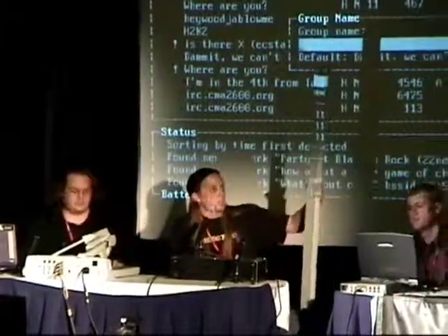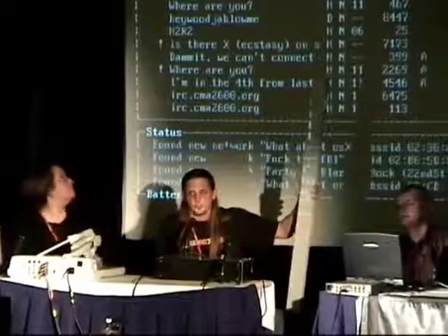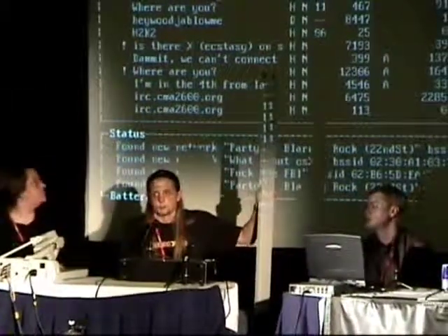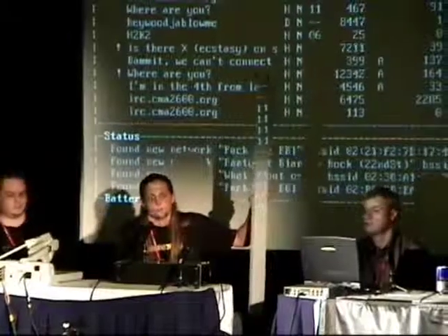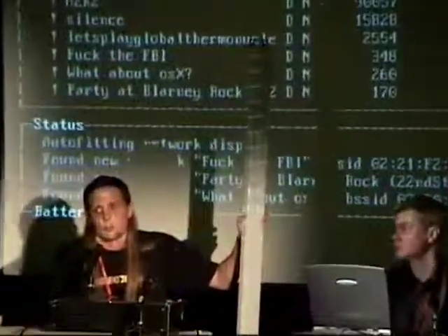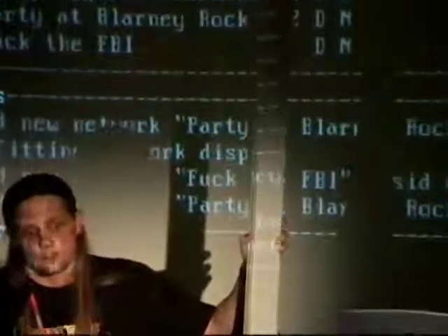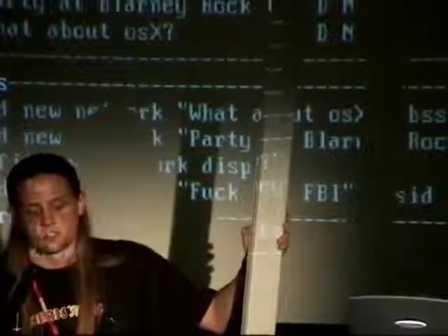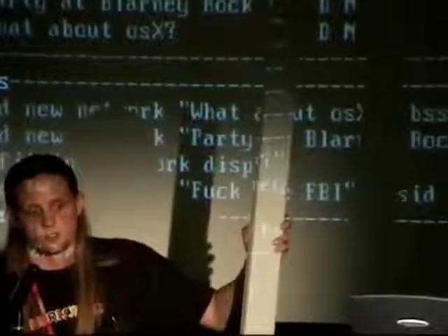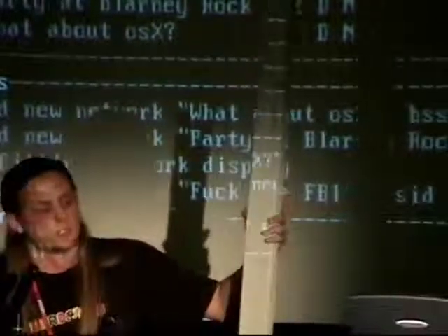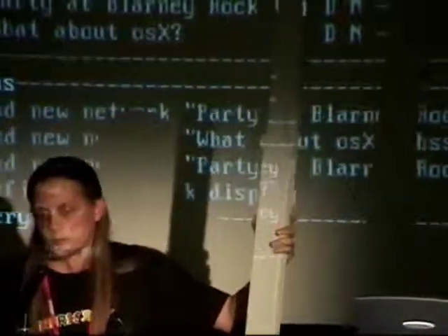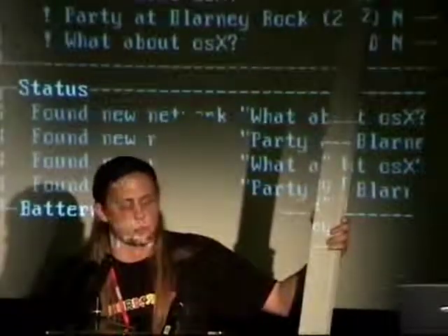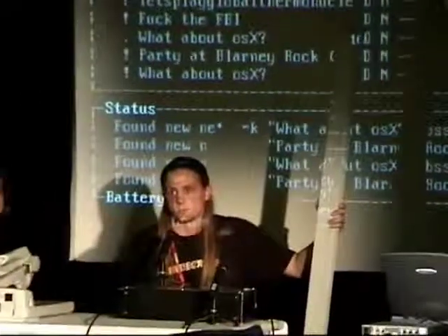All right. You've probably seen something like this, just a little bit larger than this version, on the top of buildings all over the place. It's a sector antenna. It will cover roughly 1/3 of a 360-degree circle. The idea being that you put 3 of these or 6 of these around in a circle or in a triangle formation. This particular one, I believe, is the most powerful antenna we have. It's 18 dB, and we don't actually use it a whole lot because it's kind of unwieldy.